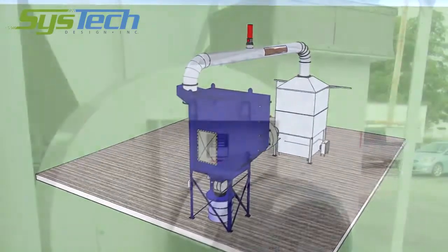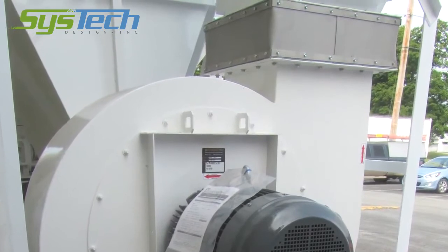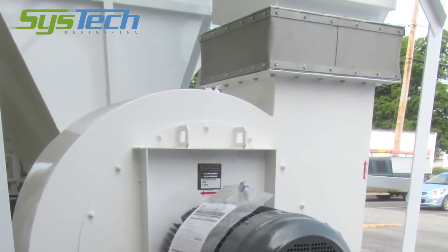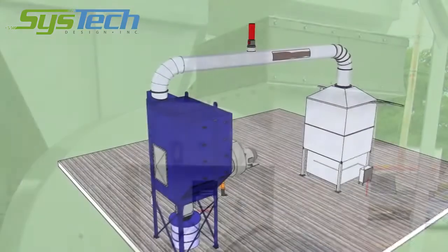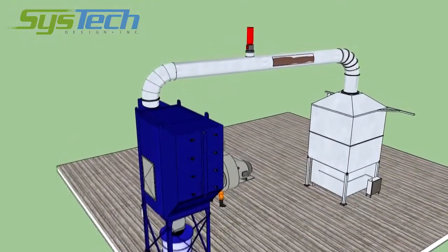While on the subject of noise, use of acoustic flex connectors is a requirement. Light-duty rubber flex joints offer little noise attenuation and will add breakout noise into any room.